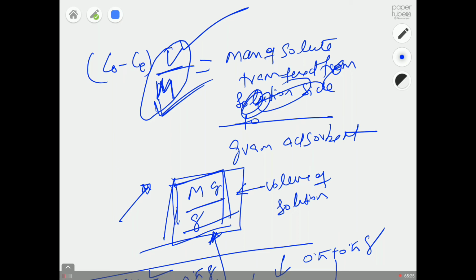You don't have to ask for 2000 liters of that solution. All you can do is run 8 different experiments, say 25 ml each, and add activated carbon. Calculate the milligrams per gram in each experiment, and it's going to be exactly the same if you perform the same experiment in the industrial scale reactor.